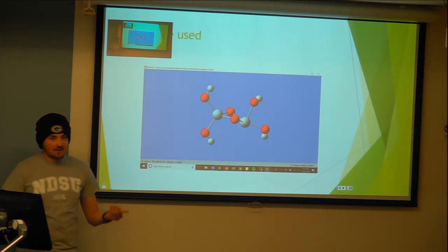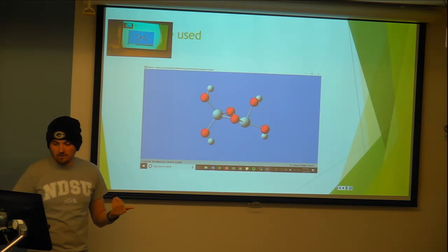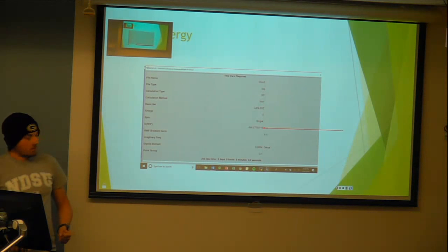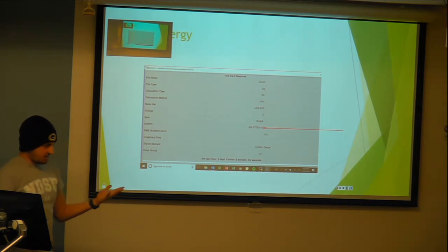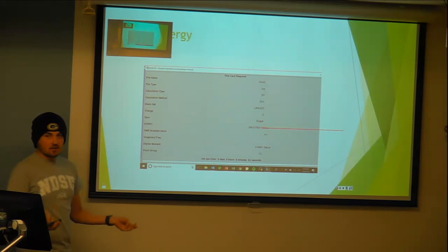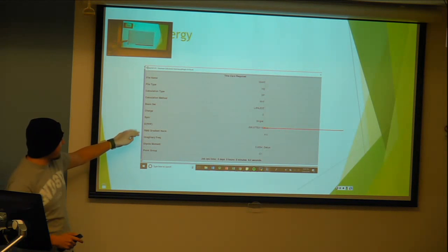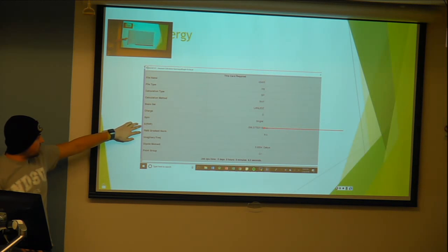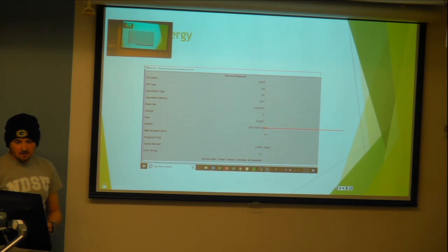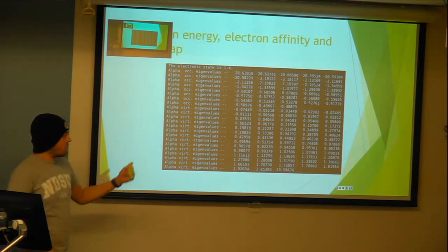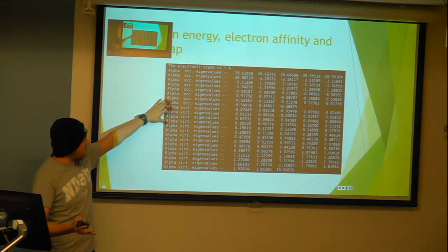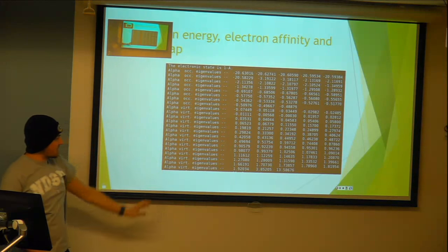So just to show the molecule I used, it's the same one we've been using for all our homeworks basically, some sort of titanium dioxide. After running the Hartree-Fock, which we've talked about this whole time, you go back in your GaussView, right-click on your screen, and you'll pull up some of your results in the summary. If you want to find your total energy, you look at this right here, and this is where you'll find your total energy after running everything. Then if you open up your file more in Gaussian or in the terminal, you'll find all these numbers towards the bottom.